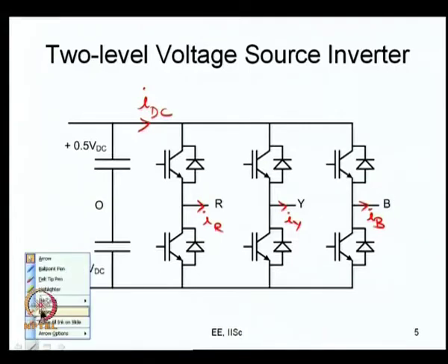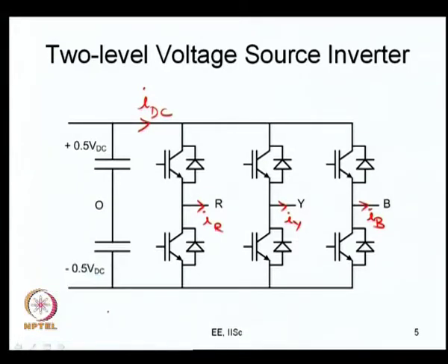So, why is DC link current important? Let us say there is some power supply which will primarily provide a DC component. Now, this DC link current also has a ripple component, and that will be supplied by the capacitor, which I call I cap. So, this I cap is also very important. That is one of the reasons why you should do this: you should know what is the RMS value of this.